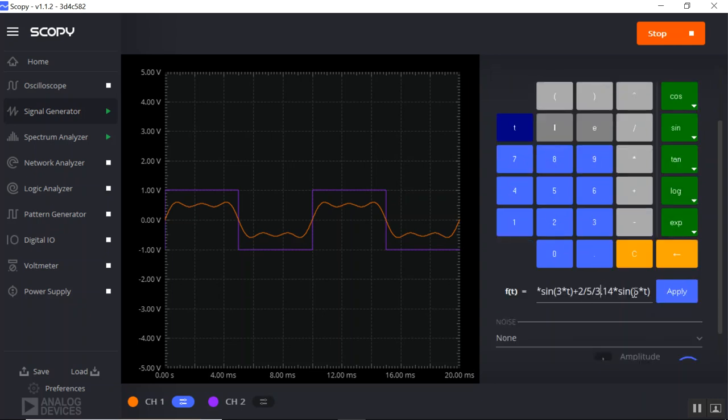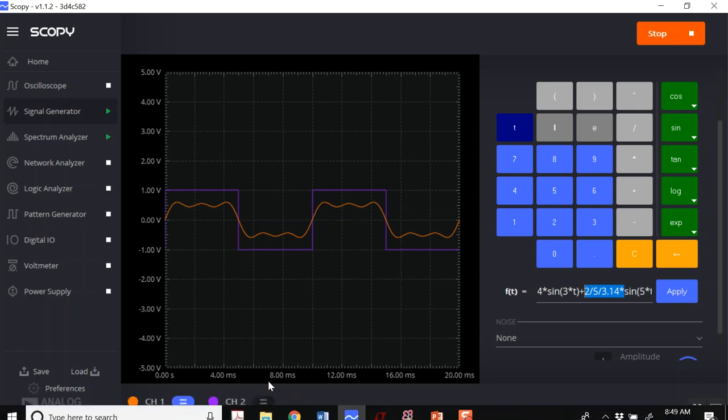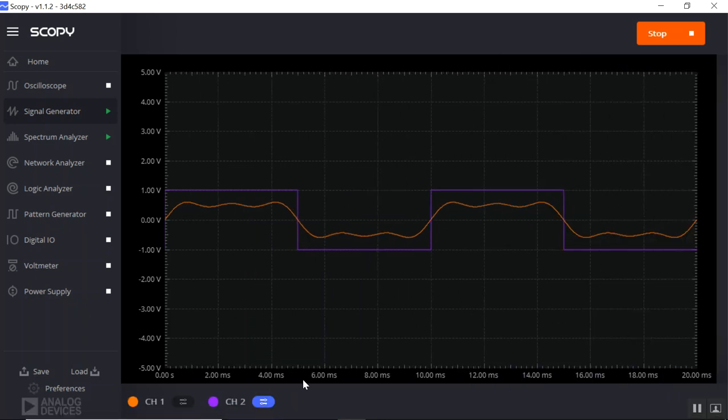And what I have here are a progression of sine waves, one at 100, one at 300, one at 500, and I'm scaling it by these Fourier coefficients. And notice how, when I start summing these up, it's starting to look like a square wave.